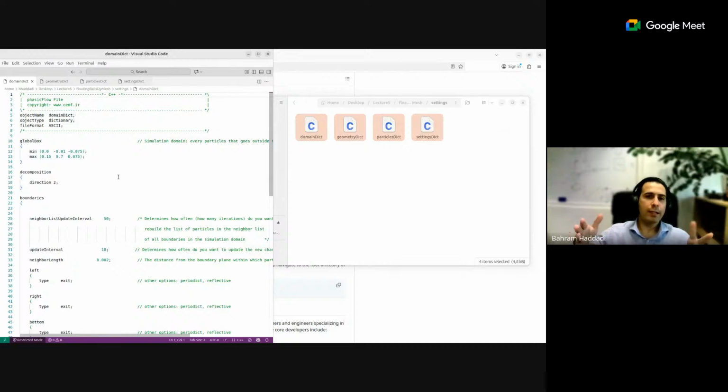We can first do a DEM simulation to drop a few particles into this box without any airflow or any fluid flow from the bottom. And as soon as the particles are at the bottom, then we start blowing the water or pushing the water or blowing air from the bottom. So from a DEM simulation, we switch to a CFD-DEM simulation. And again, later on, we can go, for example, to a pure CFD simulation, which we are not going to do today. Good. Hamid, do you want to add anything to this part?